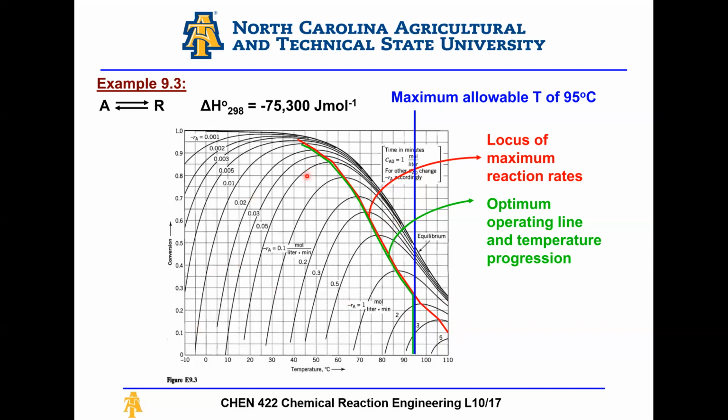And as you can see, there are two things to note on this chart. The very first top line here, which is the big curve extending from 1 all the way to here, you see it's pointed by equilibrium. This is actually your equilibrium conversion. So this line right here is actually XA versus T. And at equilibrium, so basically at rate equals 0, XA versus T represents the very top curve here.